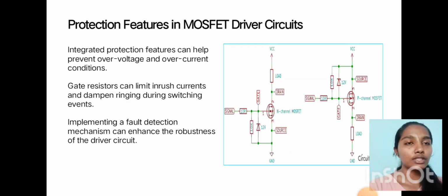Protection features in MOSFET driver circuits. Integrated protection features can help prevent overvoltage and overcurrent conditions. A gate resistor can limit inrush currents and dampen ringing during switching events. Implementing a fault detection mechanism can enhance the robustness of the driver circuit.